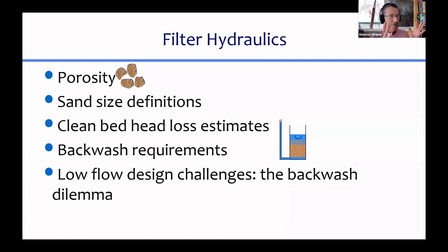So today, now that we've seen fluidized beds, I want to go over some concepts that are important for understanding how filters work, ranging from porosity, sand size, the head loss, how much pressure drop there is as a fluid moves through porous media, and how much fluid you have to push up through a sand bed in order to fluidize it. So we'll do the math for that, and what's lovely is it's a relatively straightforward calculation to get a very good estimate of that.